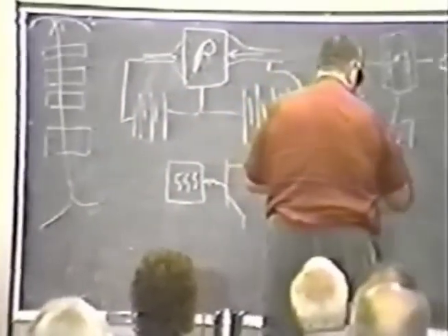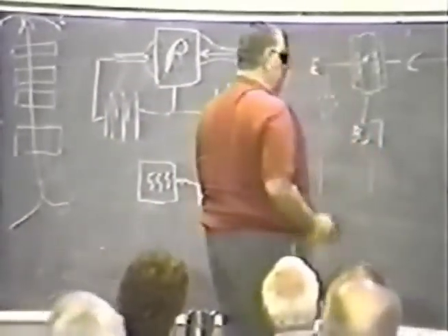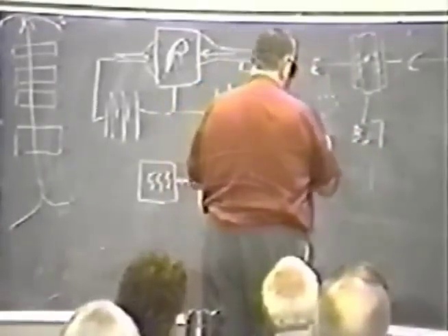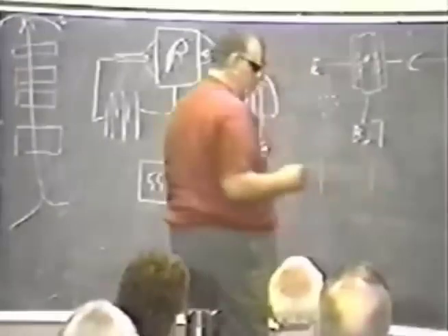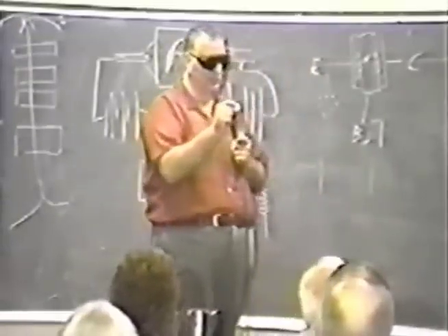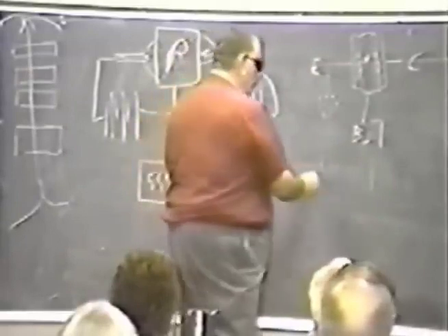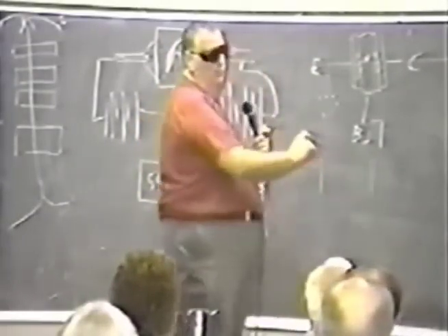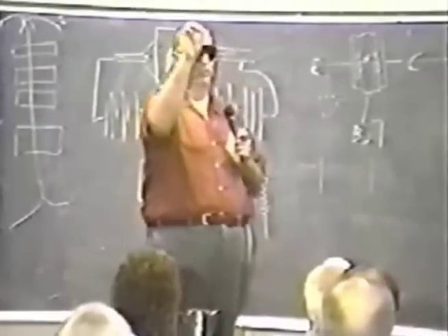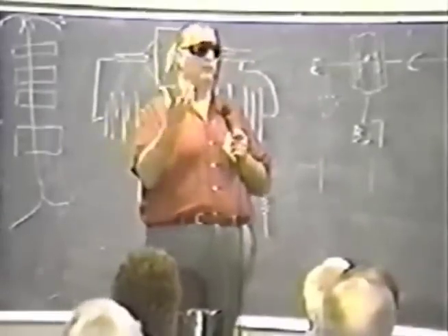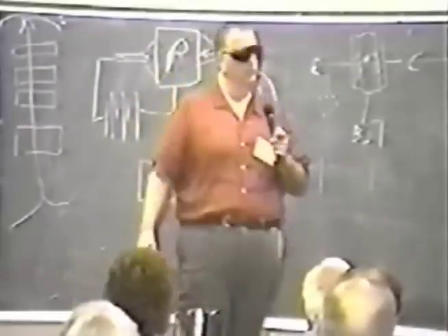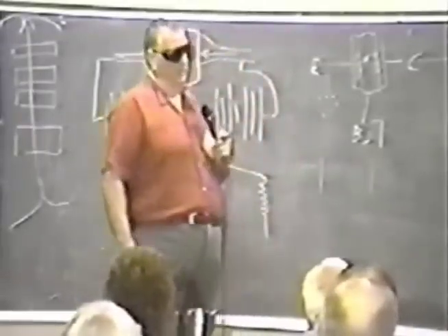You take your coil form. You rotate it. You take your feed, and it goes up and down each time it rotates. What you get is you build up a winding a little at a time, and you do 4 of these. Each one is called a pi winding. It's called pi because it goes from 0 to 360 degrees each time the form rotates once. And you just keep taking about number 60 wire, and you build it up.